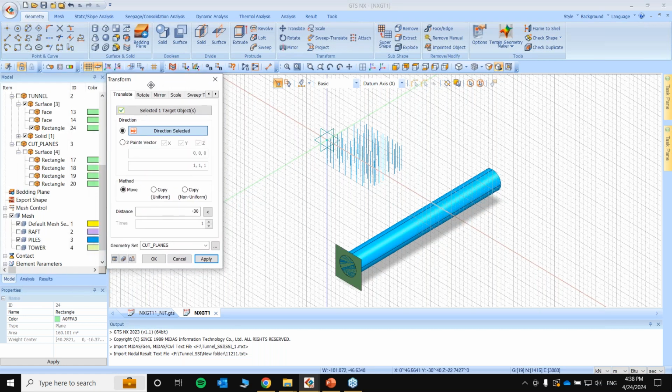So there are multiple ways of going forward with this. Okay. So the total length is 70 meters, right? So what I can do is use the first two progressions to be 2 meters, and in between I will have 22 progressions of 3 meters each, giving a total combined length of 70 meters. Okay.